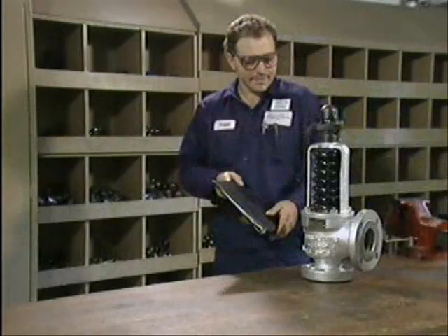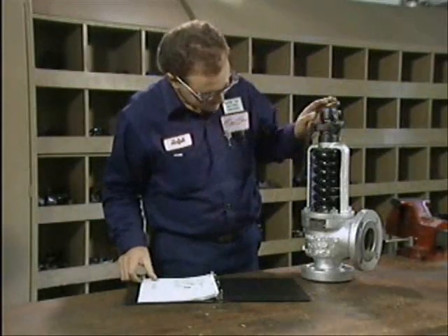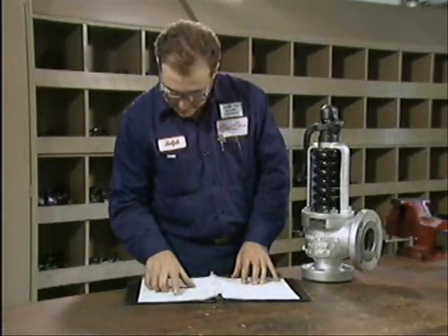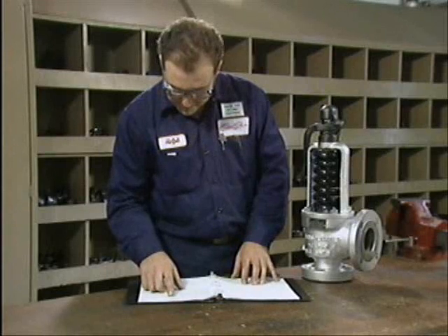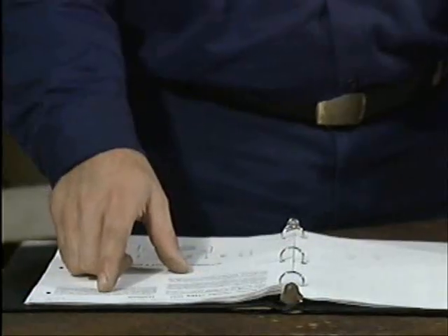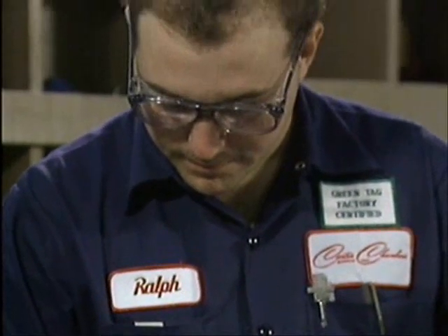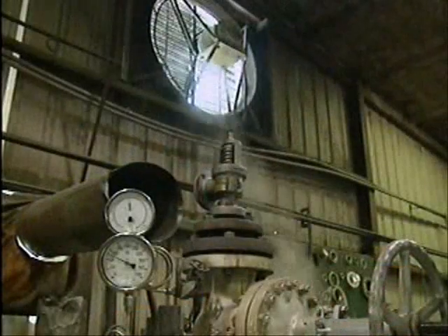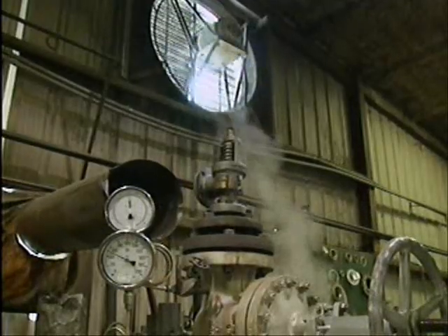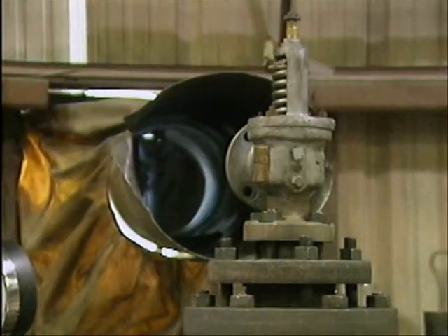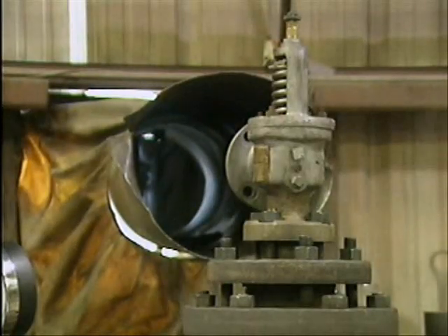Once you've completely reassembled a safety valve, you must test it to make sure that it's working properly before you return it to service. As with all other aspects of safety valve maintenance, you must follow your facility's procedures or the manufacturer's instructions for the specific valve that you're testing. But we can cover some general concerns that apply to most valve testing situations. Before you can test the valve, you must reinstall it. Take the appropriate safety precautions and follow your facility's procedures to make sure that the installation is done correctly, so you prevent leakage and other problems.